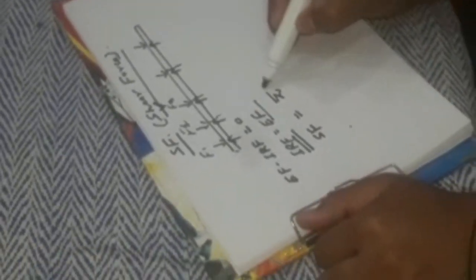So basically we can say for the equilibrium of this section of the beam, external force minus internal resisting force should be equal to 0, right? So internal resisting force equals external force. This internal vertical resisting force is the shear force, and the external force is the summation of all vertical unbalanced forces.